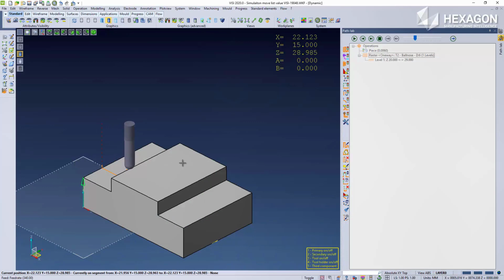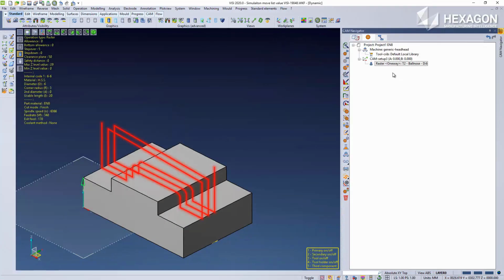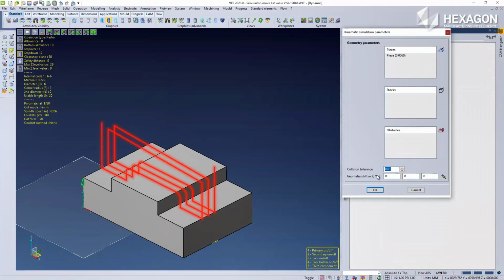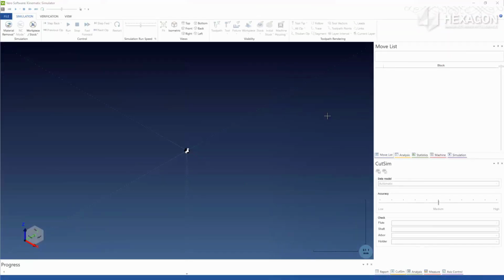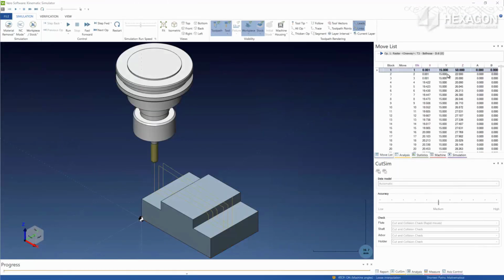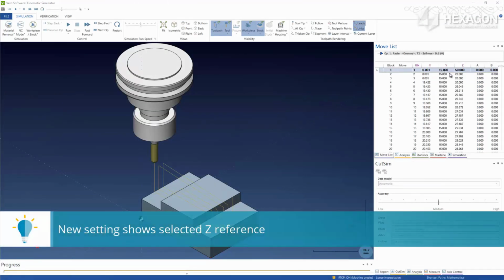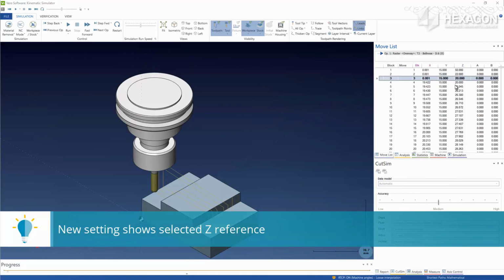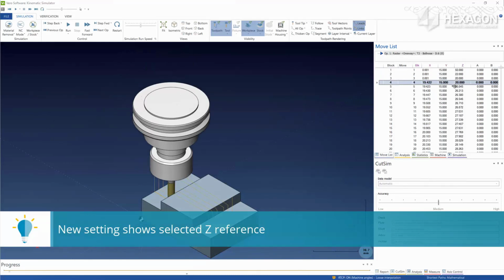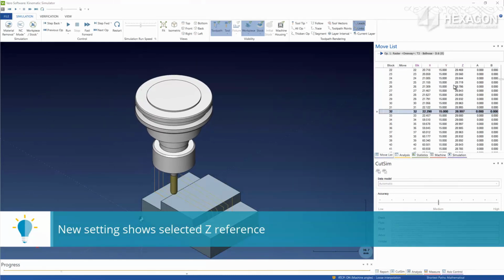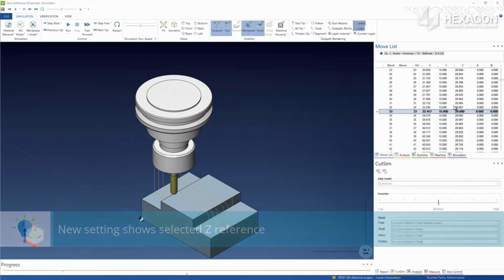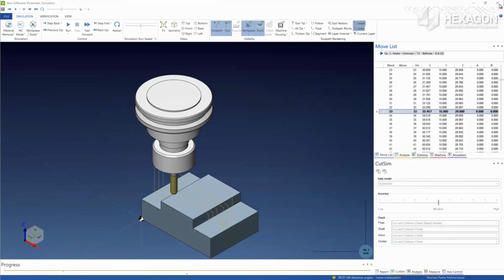So we still have our number 29. Looks good in there in Toolpath Lab. Doesn't affect that. But what we will affect is going to be the kinematic simulation. So once that loads, you can see we now have a reference as it should be. Again, it's in the CAM settings and toolpath simulation settings.